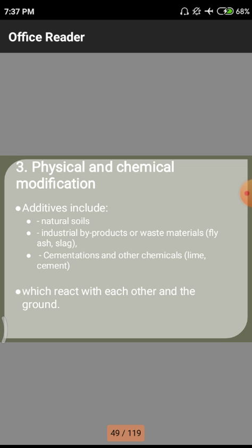Those things are waste and they have to be dumped as huge amounts of fill-like materials. In olden days they had no utilization, but after 2006 and so on, a huge number of applications were developed with these waste materials coming from those industries. We use them for construction of bricks like fly ash bricks and others. Nowadays we are using GGBS and other things also in filling for different roads and others. Next one we have cementation and other chemicals.